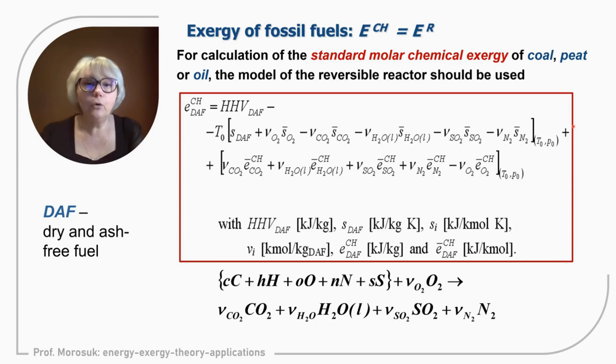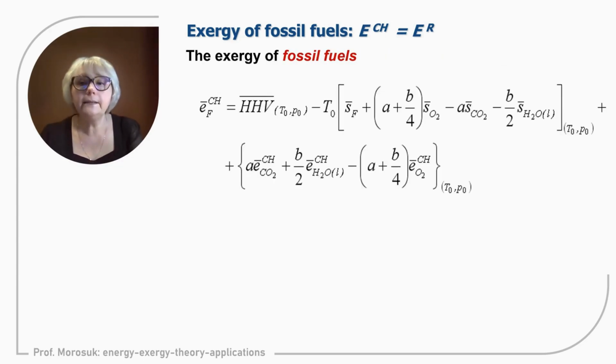And also, if we would like to abbreviate chemical exergy only with higher heating value, the higher heating value should be calculated not for the real fuel, but for the fuel under the assumption that it is dry and ash-free. And let us proceed further with this equation.